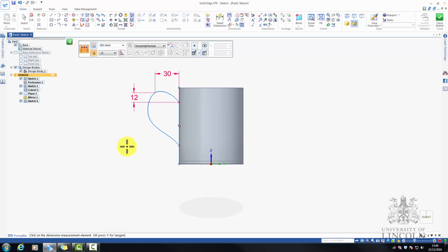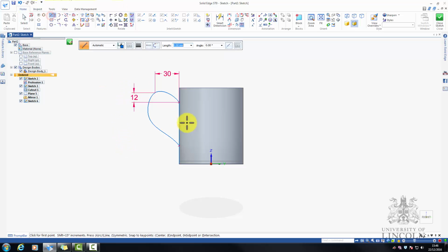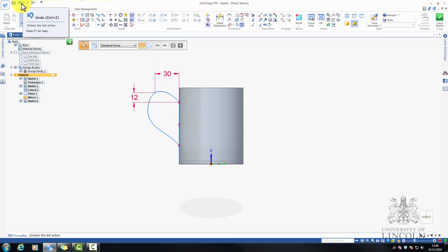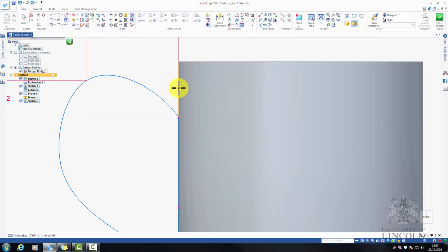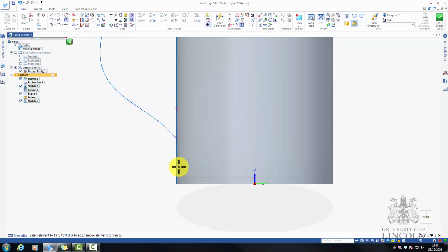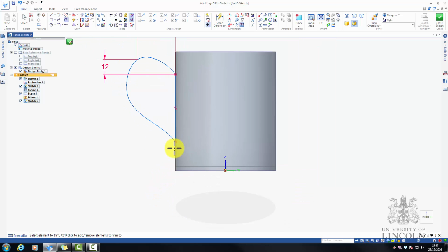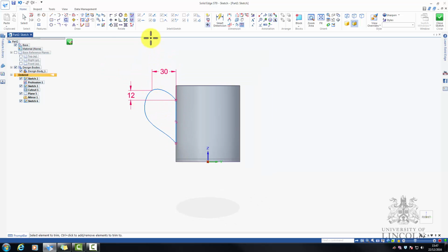Now what I need to do is work on making sure that my cup handle is fully closed up, so we've got from point to point. So I've just created a new line in between, but maybe that's a lazy way of doing it. Maybe that's too fast. It would be more elegant to undo that action and perhaps even trim our way to it just to check that our shape is closed. You can see here I can select just the top. So I've trimmed there and I've trimmed here. It's gone to a square relationship, so that means it's a closed section. This is again good news.